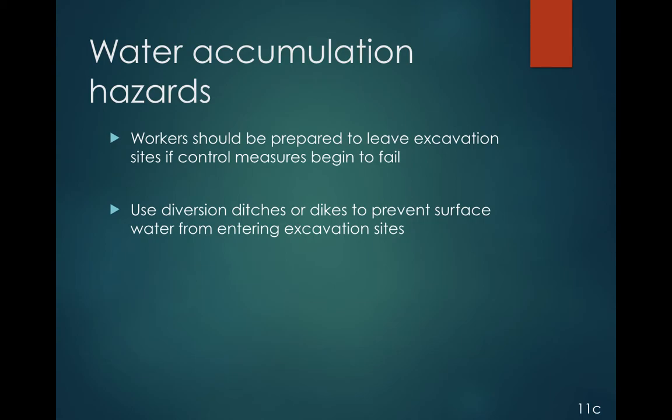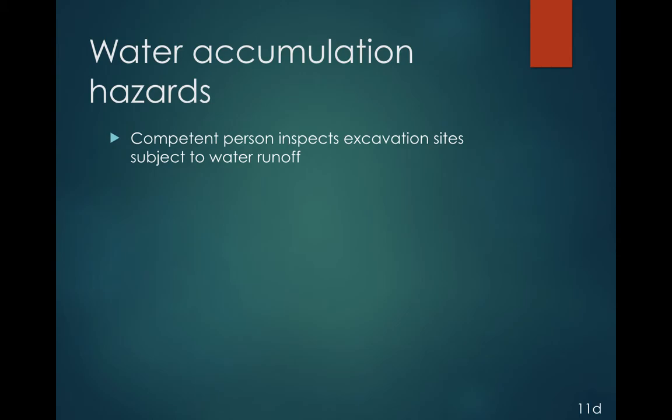Use diversion ditches or dikes to prevent surface water from entering excavation sites. A competent person inspects excavation sites subject to water runoff.